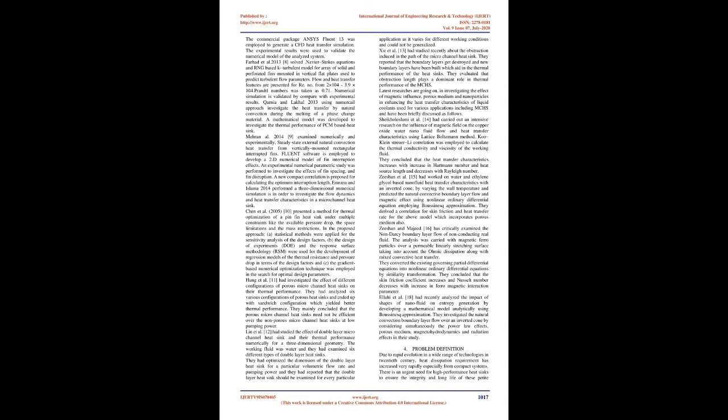Farhad et al. 2013, 8. Solved Navier-Stokes equations and the RNG-based k-epsilon turbulence model for an array of solid and perforated fins mounted on vertical flat plates, used to predict turbulent flow parameters. Flow and heat transfer features are presented for Re from 2 × 10^4 to 3.9 × 10^4. Prandtl number was taken as 0.71. Numerical simulation is validated by comparison with experimental results.